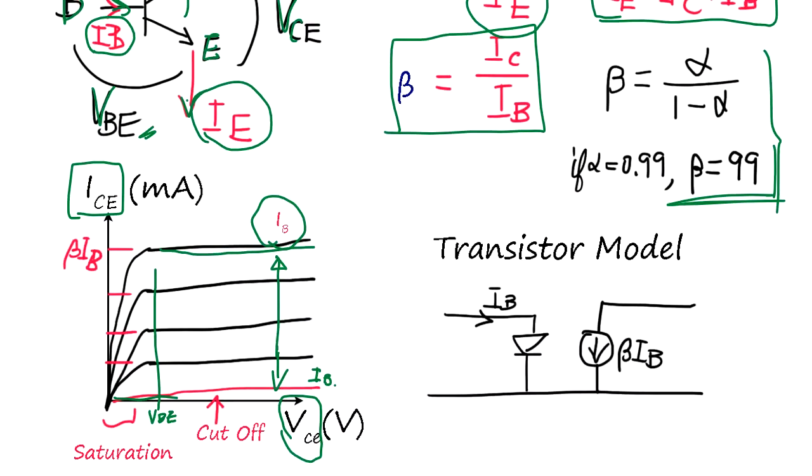If VCE becomes lower than VBE, then the characteristics start changing to be like a diode. So it's a saturation point. This range is the saturation range. Above the saturation range is the normal transistor operating range, in which IB determines IC.